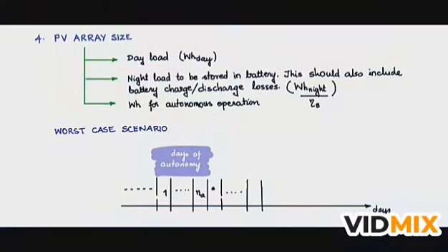The battery has to recuperate. So following those days from 1 to NR, these are the recharge days. These are the days on which the battery has to be recharged such that the watt hour lost during these days of autonomy is recuperated, is replenished. The watt hour lost during the days of autonomy is, let us say, given by WH auto, and the entire WH auto may not be possible to be replenished in one day.